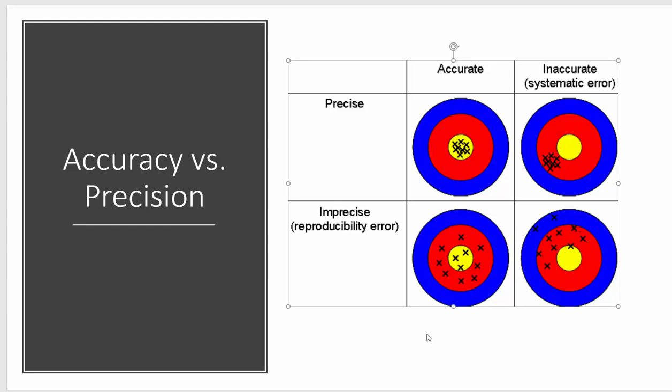Sometimes if the equipment is old or malfunctioning, you can have results that are accurate but imprecise. You can have measurement results all over the place, but when you do the average, it still comes at the center. So that's why it's accurate but not precise. And then there's the worst case scenario, where it's neither accurate nor precise. So this is a qualitative description of accuracy and precision.